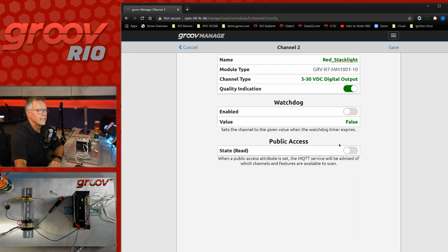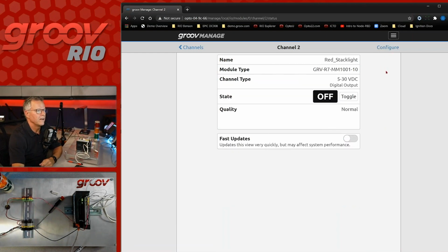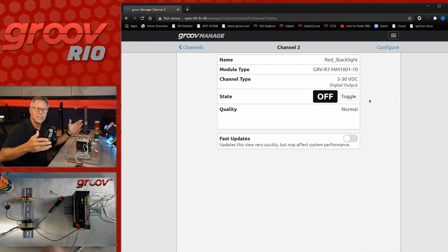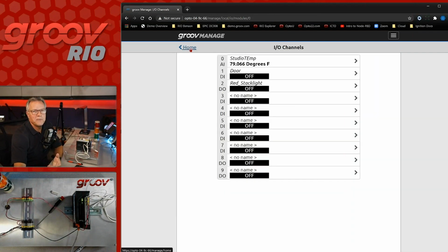Okay, perfect. Now, again, I want to know the state of it, but I really care about writing to it because I'm going to let Doug actually post on a topic, on a Sparkplug topic, which the Rio, I should say, will subscribe to and make a change. So we'll actually see Doug control my stack light from Pennsylvania. Okay, I'll hit save. The beauty of this as well is I can toggle it on and off. There you can see my lights going on and off. So I've tested and commissioned my IO. I'm all set.